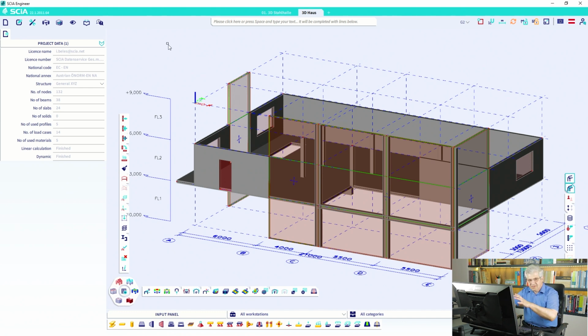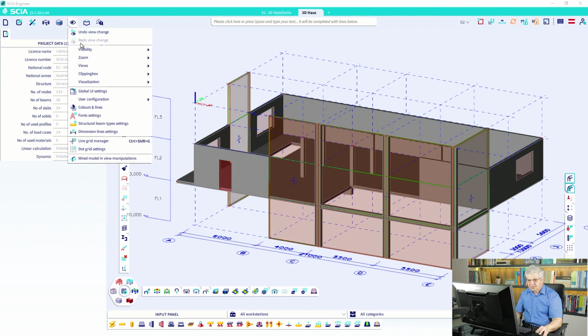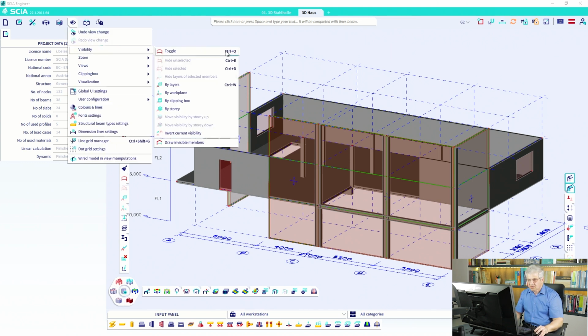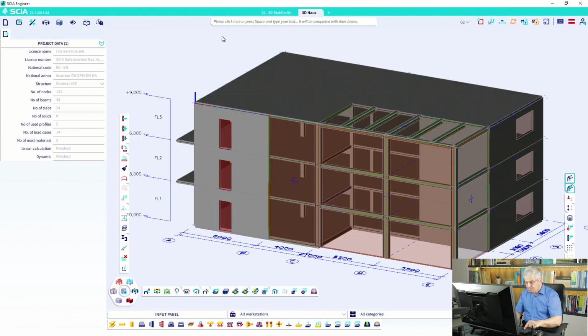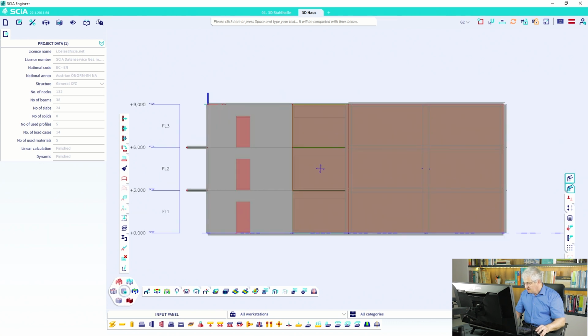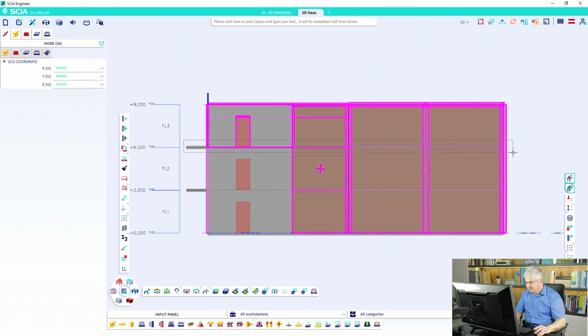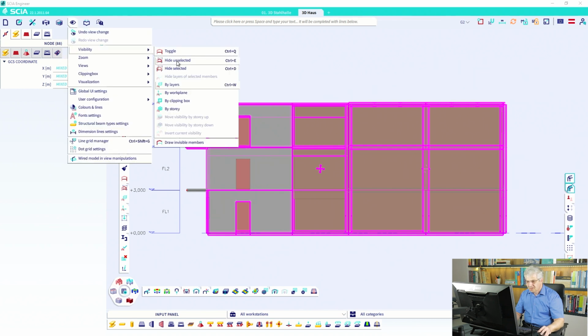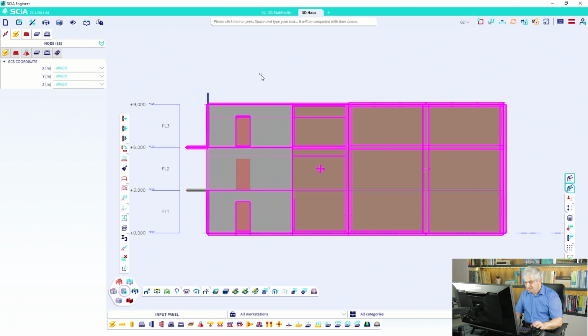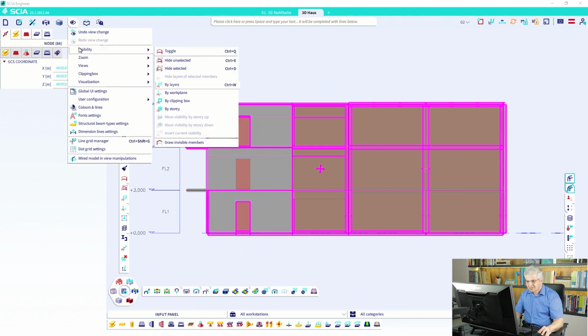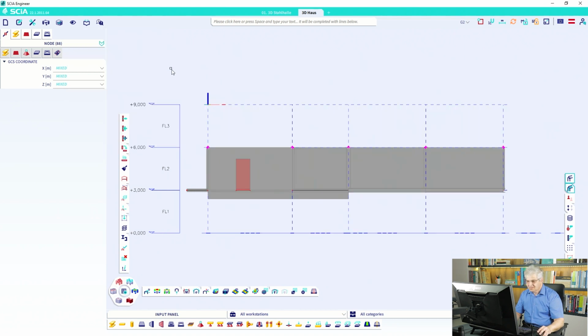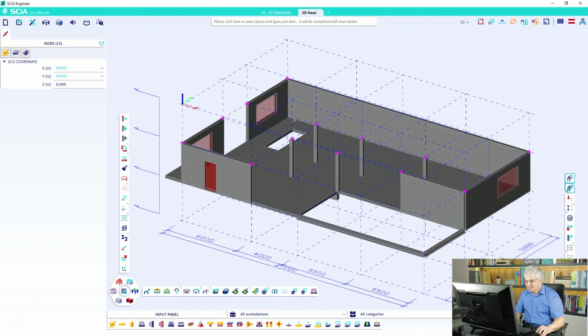It also works the opposite way. So if you want to have then the full structure visible, then go to visibility toggle. It's Control Q. You can remember it very quickly. Control Q, you see everything. So go for front view again. You can also select this plate from left to right, and these walls from right to left. And it was, I think, Control E, hide unselect. No, back. Hide selected. It's the opposite way. So I did it the opposite way.